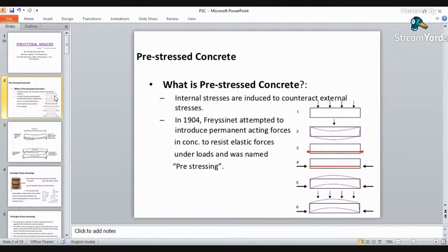When we are talking about conventional reinforced concrete, it doesn't have any compression when it is put into service. So it will deflect too much, well before it is time for danger, or before it is in a strong enough condition to hold enough load. So with conventional concrete, we don't even get the full advantage of the structural strength of the member. But when you deal with pre-stressed reinforcement within the concrete, we do not necessarily increase its strength, but we reduce its deflection.